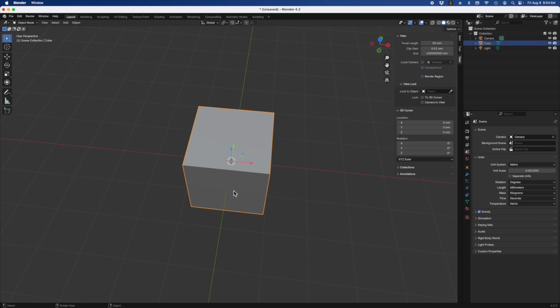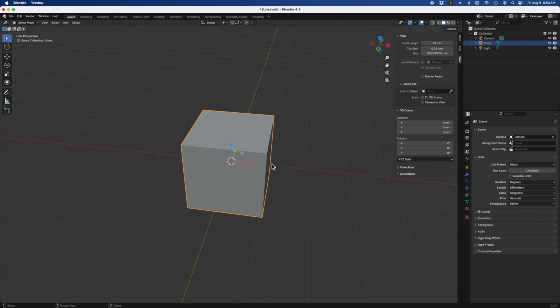Now that's how we work in millimeters. We set up Blender to work in millimeters. From that particular point, what I want you to do is come over to File, and go down to the Defaults menu option here, and then Save Startup File.